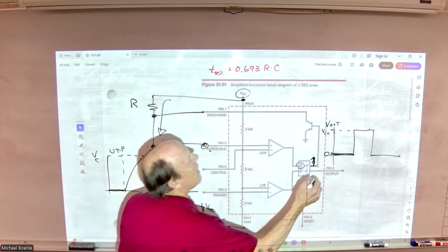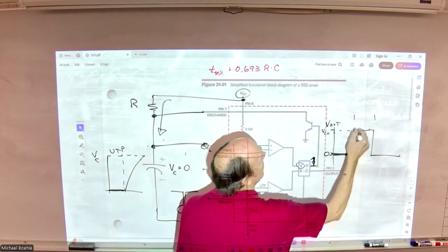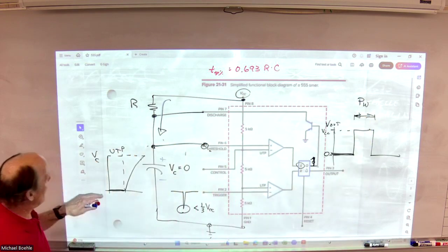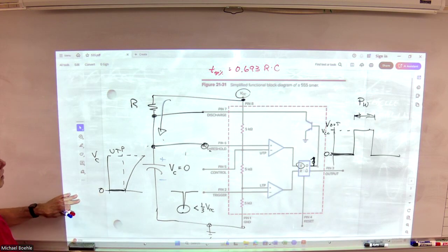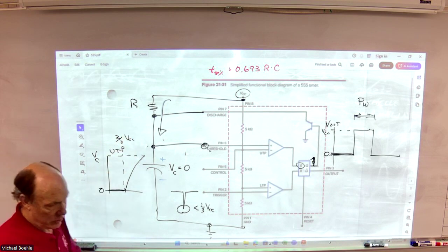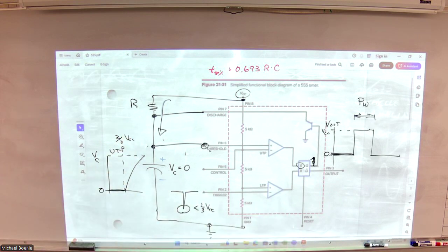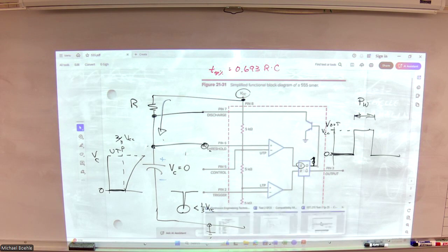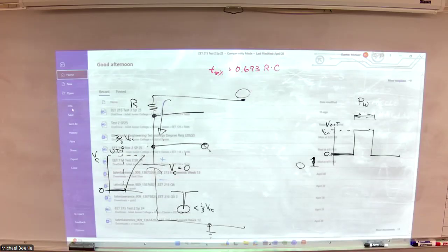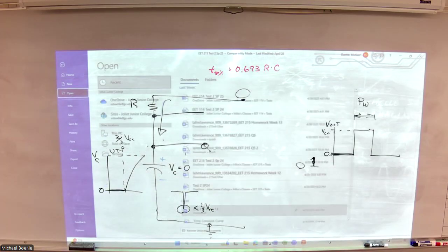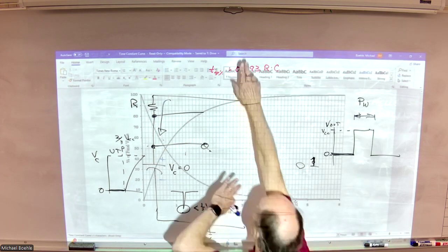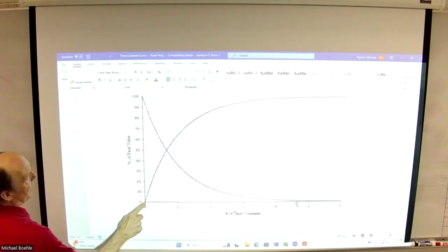Now, the amount of time, the pulse width, is determined by how long it takes to charge from 0 to 2/3 of VCC. That was 2 weeks ago, right? We had that universal time constant curve up. Let's see if I can find it here real quick. Oh, there we are. Perfect. So this is my curve.